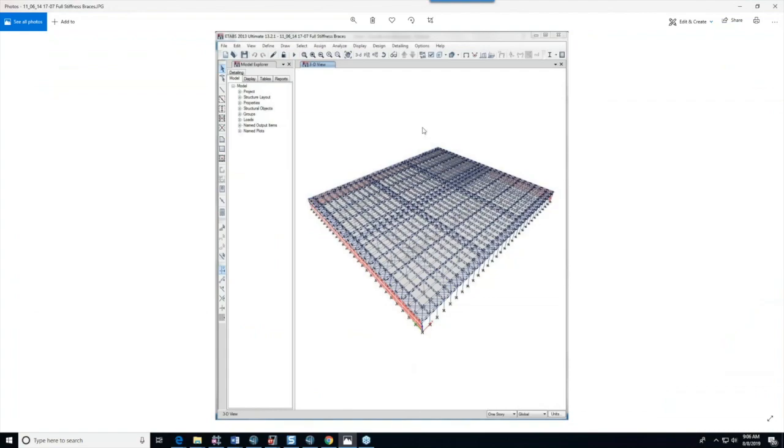So here's one. This is like a large one of these box retail stores, or could be a large warehouse. And I know you have all seen these types of structures. They typically have very tall fluted decks. And the reason the ribs are quite tall is because they have to channel a lot of water a long distance, and you form a pretty deep trough with water.